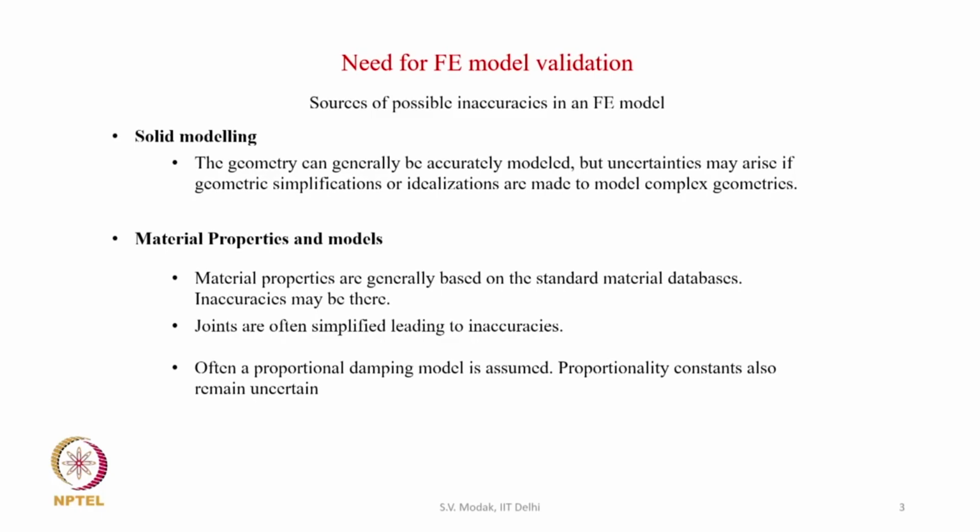Often the damping in the FE model is taken as a proportional damping model in the absence of an accurate model representing the damping. So, that is a source of error. Also in the proportional damping model, values of the proportionality constants are generally not correctly known, right, and therefore their values again are uncertain and a source of modeling inaccuracy.